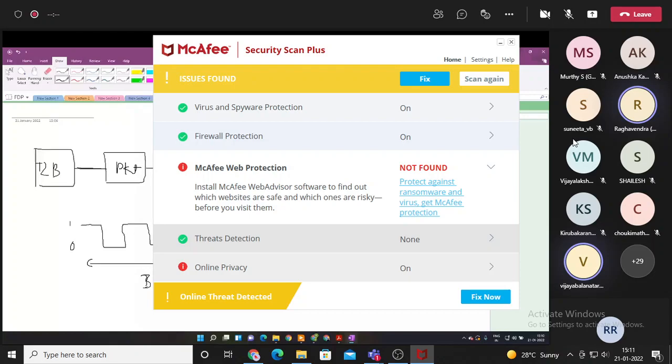We really don't want that to happen, because when that gets decoded, you just get gibberish, you get noise, and not something that we would like to display. Imagine having a WhatsApp message where you just keep getting gibberish because nobody's sending anything. We don't want that, right? So what we do instead is Manchester coding, where one bit is represented by 2 different levels in your signal. So it's either this or this. During an off state, since it's always off, this is not considered a signal at all. The receiver understands that this is an off state, which is why we do Manchester coding at this point.